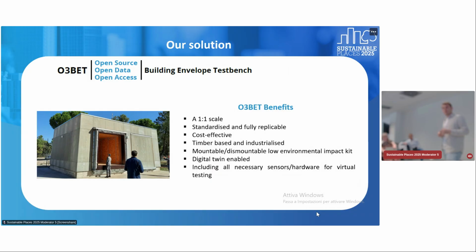This one is better suited for thermal characterization. I think that is the key application at the moment. The challenge of doing a standardized thermal characterization test, I believe there's an ISO, is that you need enough temperature difference between the inside of the cell and the outside of the cell to actually trigger a correct thermal characterization of your U values, for example, and the conductivity and so on. So it also depends on what kind of weather conditions you have during the test. That's why they give quite a long period to try and test it.